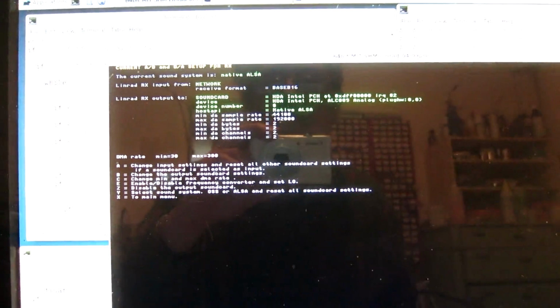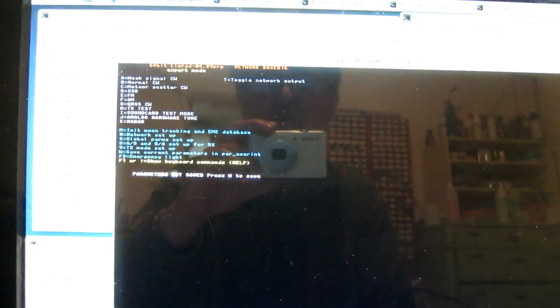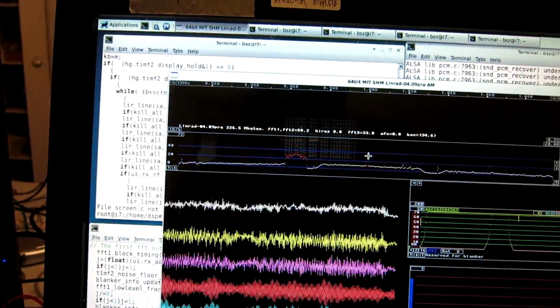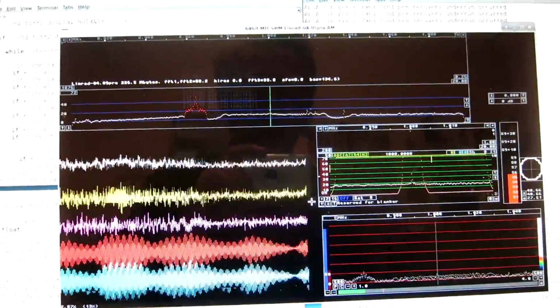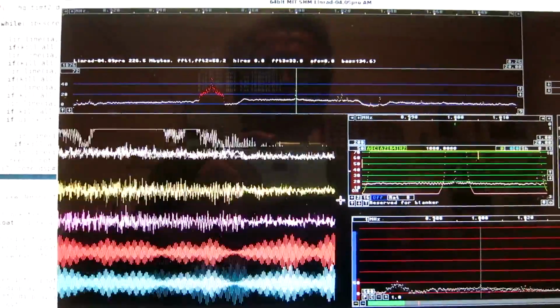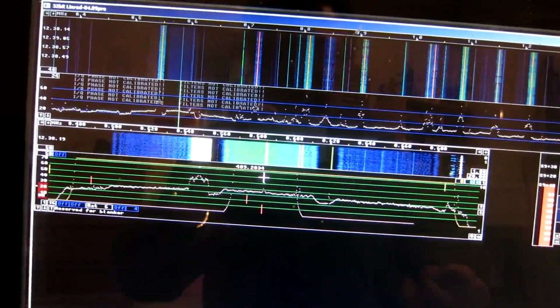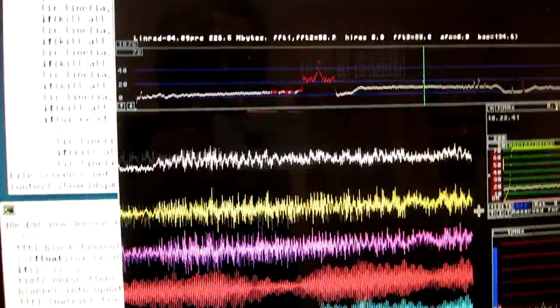And on another computer I have it set up like this. And I press F to receive amplitude modulation. And at the center here we have the signal. Now I am sending the frequency range from here to here, and I will turn down the bandwidth. I do that with the yellow mark here while looking at what comes through.